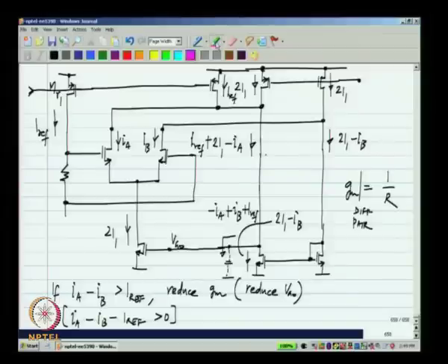Now earlier I said that first of all this is not sensitive to whether the transistor is following square law, because we have not used that anywhere. All we have assumed is that this differential voltage Vd is small enough, so that the output current of this differential pair can be represented as something being linearly related to Vd, okay. So it has to be operating in the small signal regime, that is easy enough to arrange.